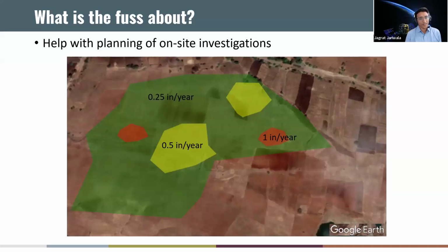Now, imagine if you have an ability to go back in time, understand how much the surface moved, and utilize that information. Now, for mine sites or landfills, geotechnically speaking, what would result in settlements is some combination of what kind of material was filled, how much compaction effort was applied to that material, and how deep were those excavations or how deep are the fill depths.